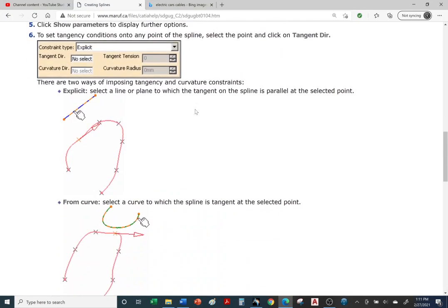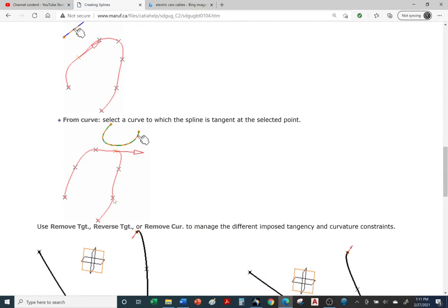So that leads to, how do we add a radius? So when we model it, there's a minimum radius that we're going to use when shaping the cables and running it through the vehicle. Once again, from near the charge port, near the tail light, going through the trunk, going through the seats and making turns along the side, going by the door frames, etc., to the firewall, and through the firewall to the front, to the battery. Okay, so you have to take that into account when you're modeling these electric cables, especially these high voltage cables.